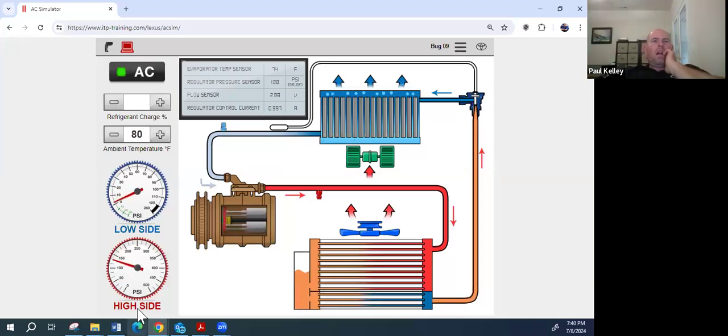Okay, these are not good. Your low side should not be just about 0 or 1. Exactly. Now, why would the low be so low? I think you already know because we were talking about moisture, right? But how could moisture cause the low to be low?